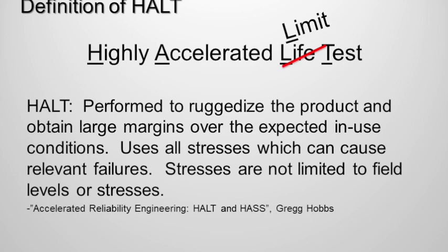So the definition of HALT is that it's a highly accelerated life test. It's actually been redefined as highly accelerated limit test. And the idea is to ruggedize the product and obtain large margins over the expected in-use conditions. It uses all stresses which can cause failures, and stresses are not limited to field levels. And that last sentence is very important, because that's one of the biggest hurdles in getting people to accept HALT, is there is a natural resistance to putting stresses on the system that far exceed the field stresses.